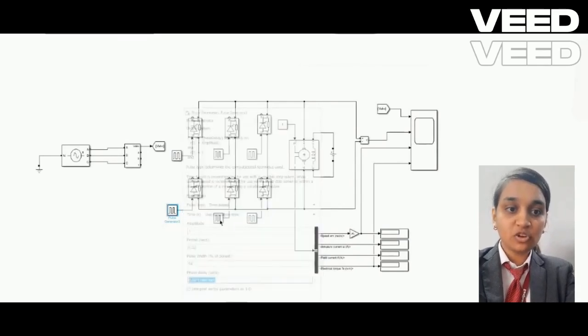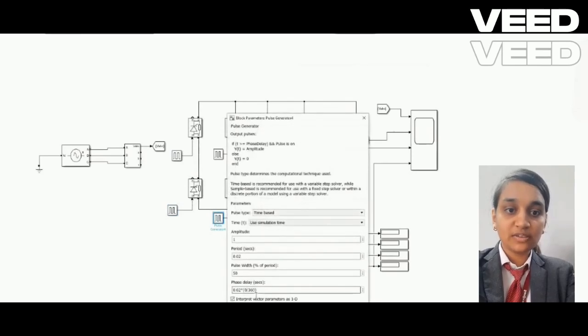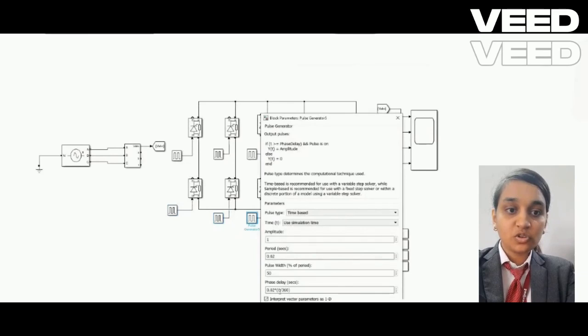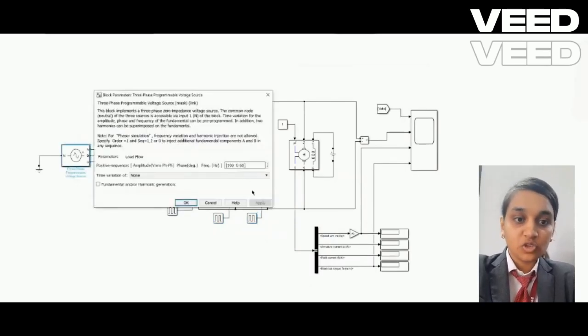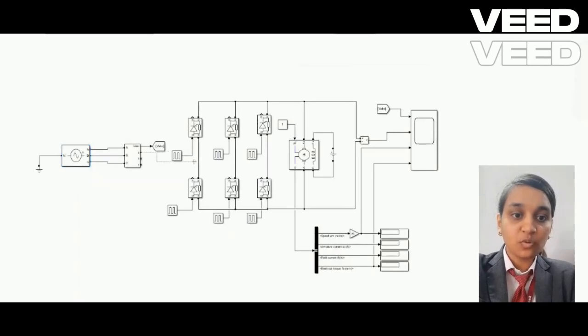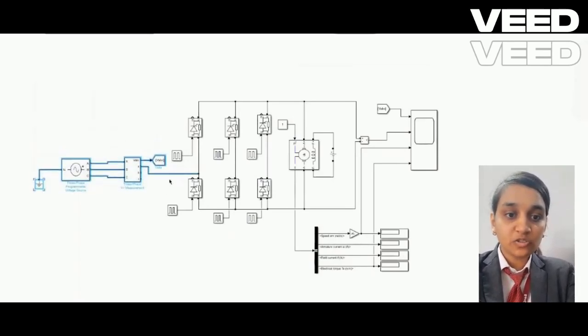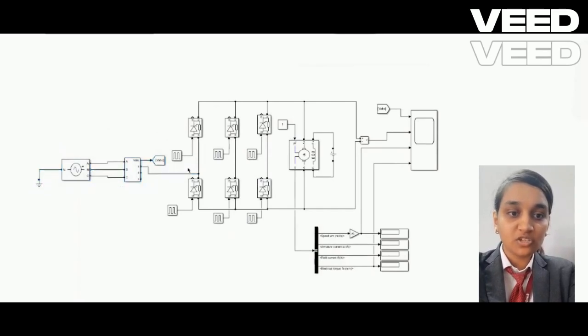The delay times are 0.123, 0.0377, 0.00717 and 0.00258 seconds, and the steady state errors are 25.6%, 0%, 25.6%, 0% respectively. Hence, the configuration in figure A is more suitable than figure B. Shown in the figure is the speed response of the DC motor for a step change of the reference speed with constant load torque.